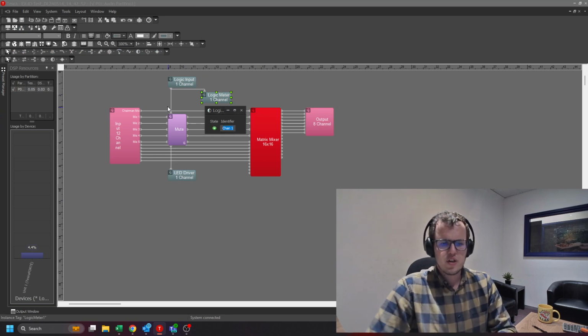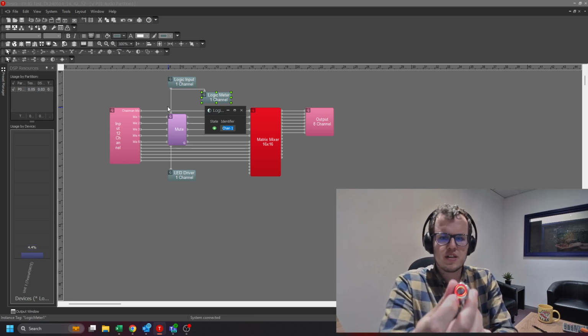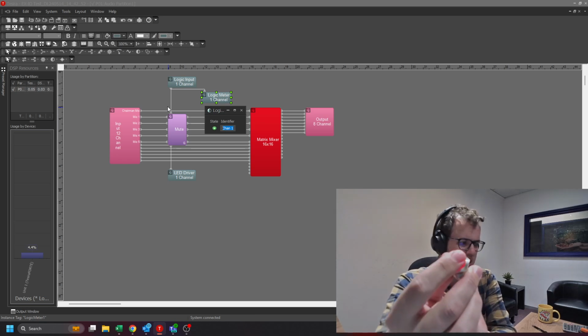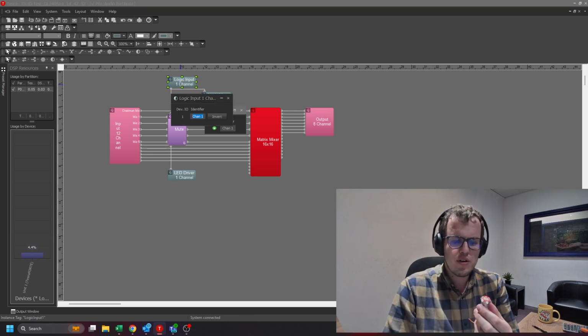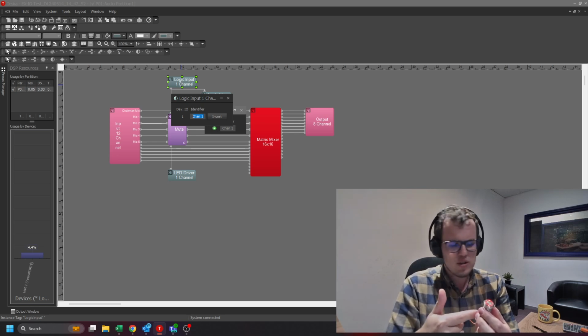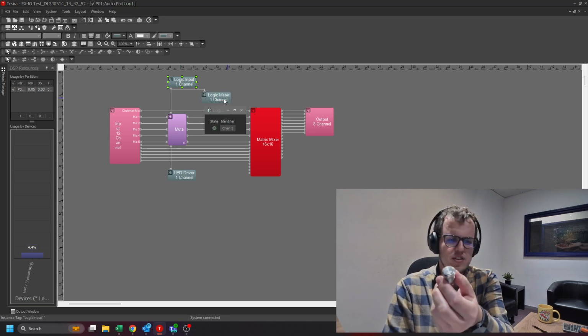So the first thing we can do is we can see the state is on, and if I look at my button, it's not currently pressed in. So that's obviously inverted, so I'm going to swap that around. You could either change it from normally open, which is wired at the moment at the back of the button, to normally closed, but it's just as easy to click in the software. So now the LED just went off.